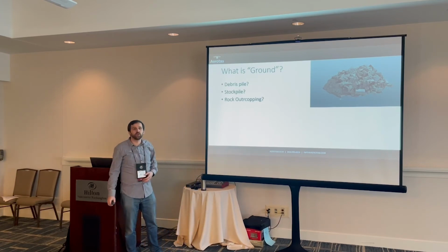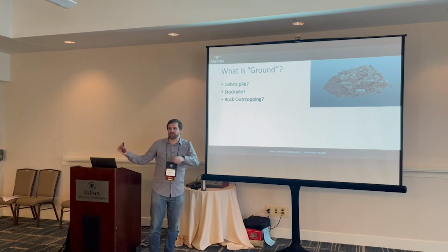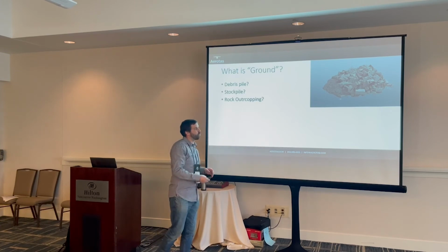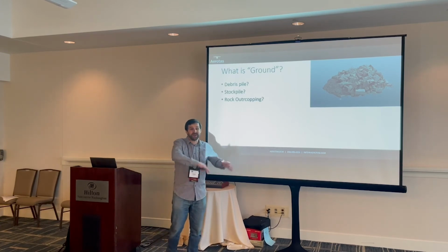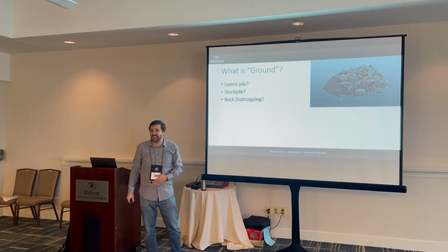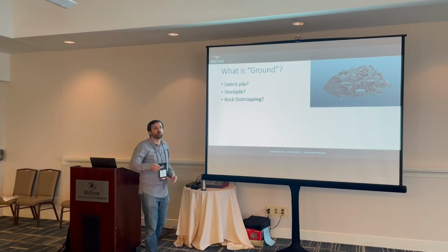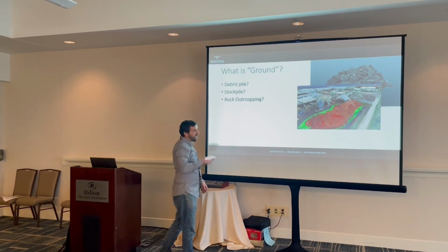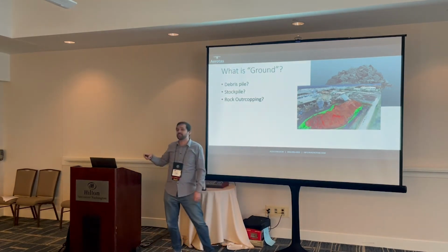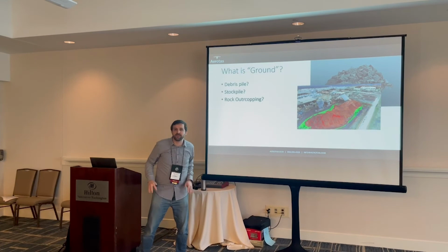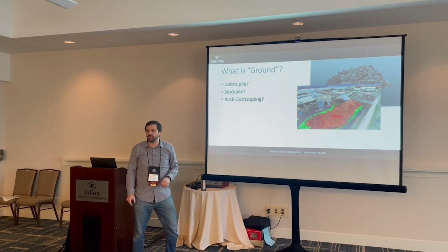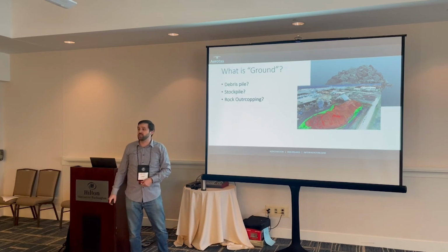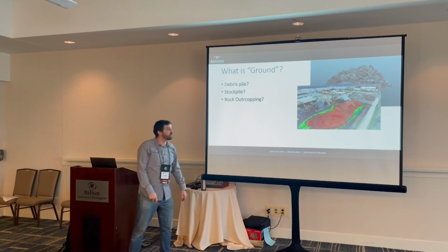In some cases you do want it to be ground. In other cases, no, that's trash. You exclude that as debris and you get the surface underneath. But that's rock and rubble, and maybe calculating that surface is what you actually care about. That's a judgment call and there's no right or wrong answer to it. Same thing with a stockpile. Is the stockpile itself ground, or is it a separate object, and you care about the ground underneath, and then you measure the volume of the stockpile as its own classification? Once again, that's a judgment call. It really depends on the type of survey that you're doing.